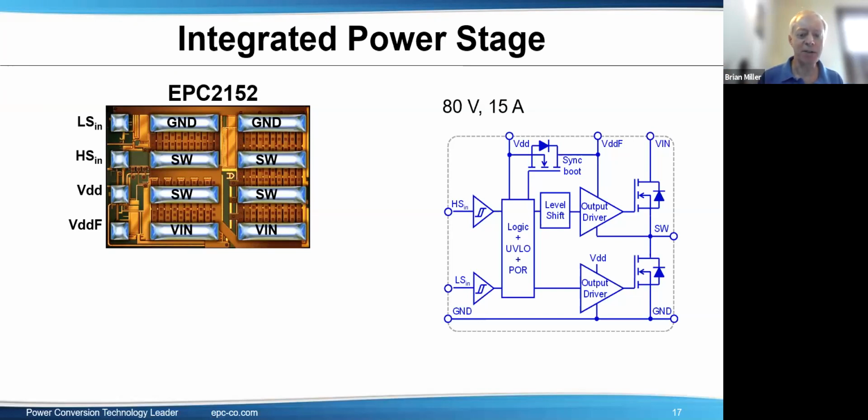The bootstrap capacitor on this part, that's a very good point too. It looks like it's there just to drive the upper gate driver. It's not shown in this diagram. It's an external capacitor right here from the gate driver down to here. So it looks like it doesn't do anything, but there is some internal logic. So yes, you do need the capacitor there. Whenever the bottom FET switches off, it will boost up here and keep the whole internal circuit running well.